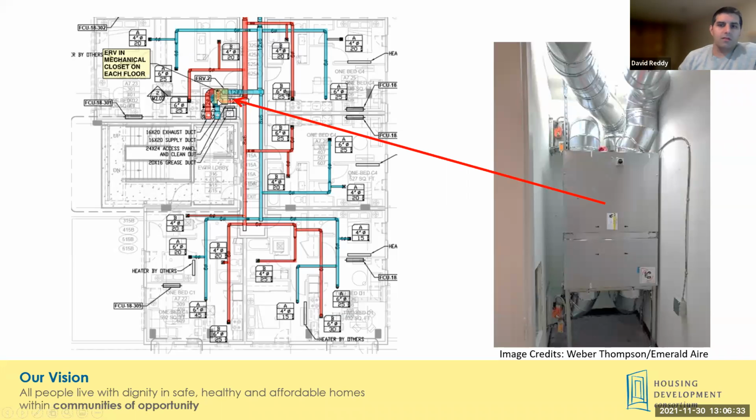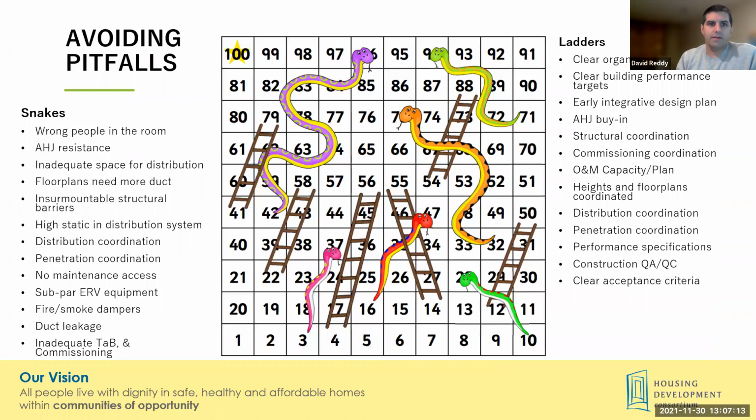So there's quite a few variations of this, and these guidelines and the work we're doing here is definitely not intended to lock you in. What we want to encourage is that you do consider variations on these concepts, but with the fundamental idea of trying to avoid fire smoke dampers and optimize the ductwork placement to within the conditioned envelope and with low distribution losses. So this is a really cool example of that.